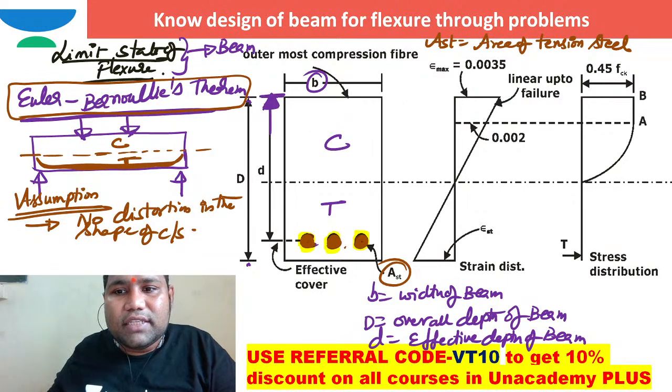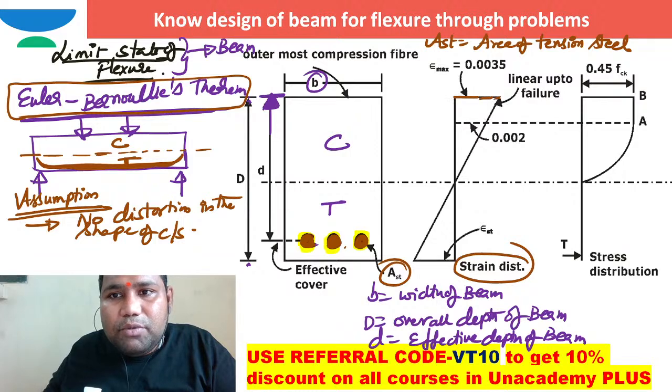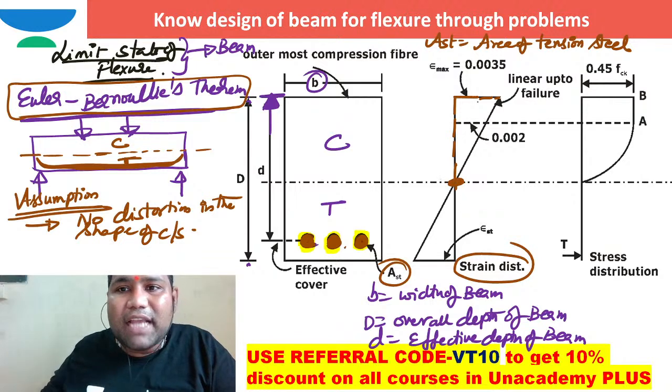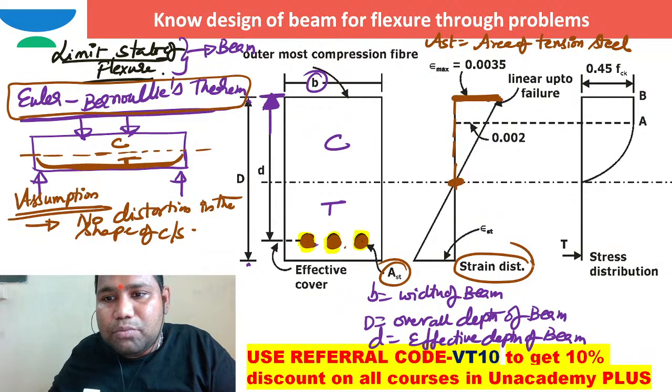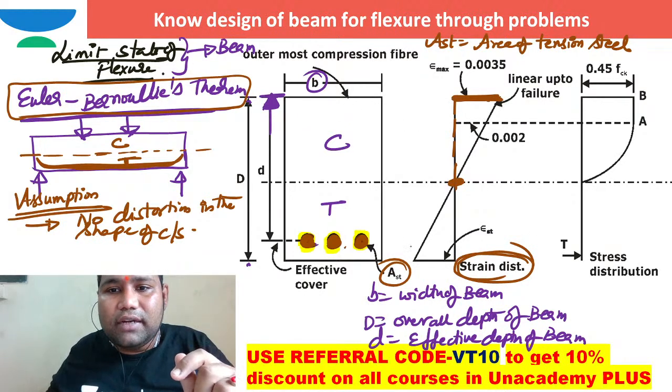As there is no distortion in the shape of the cross section, I hope you can say this is the strain distribution. Strain distribution is linear, with zero strain at the neutral axis and maximum at the extreme compression fiber. So I hope maximum strains are possible at the ends.